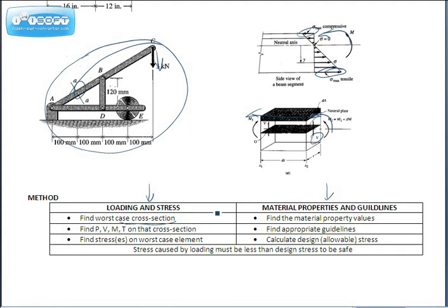It usually actually is in bending. It is not usual for a 2-force member. Usually the worst case cross section will be if there's a member in bending, so you would suspect that might be your worst case.